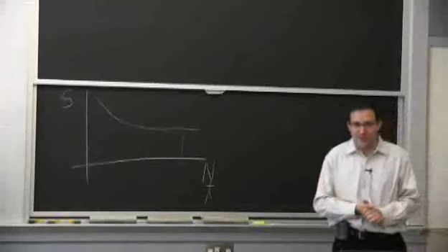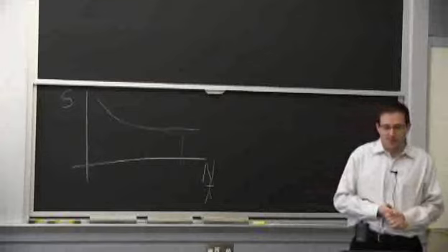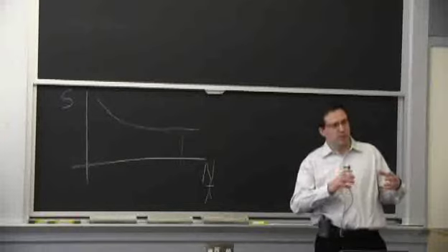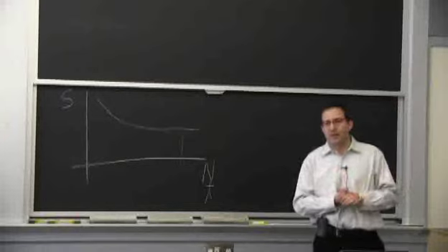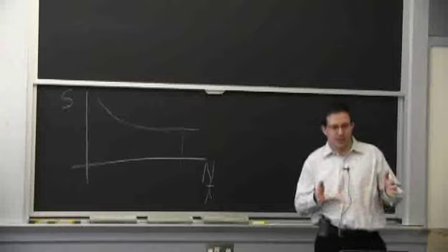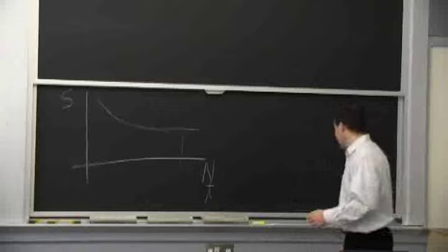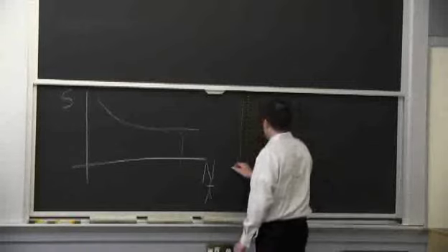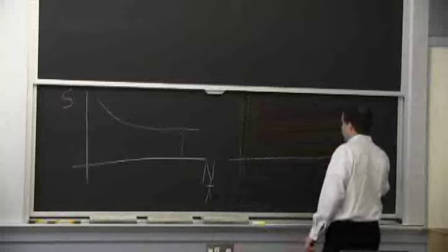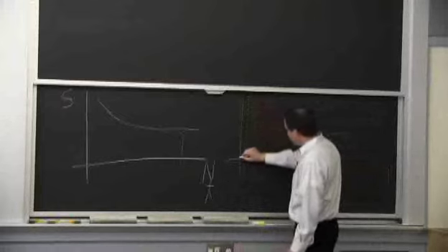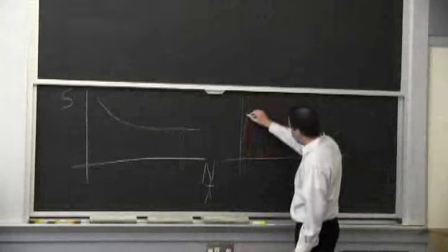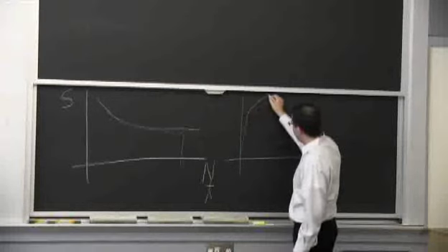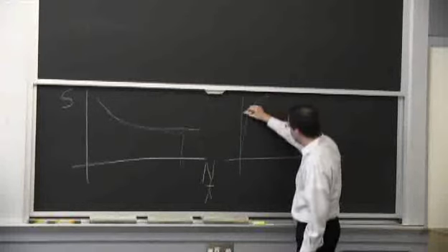Yeah, right. Yesterday we saw that it was good to preload the bolts a lot, so you'll reduce the amplitude of the stress variation when you load them. And we talked about it after the class. I'm actually going to try to explain it a slightly different way. So if we think of the stress strain curve where we have the elastic portion and then we go into plasticity, and so that's yield here.